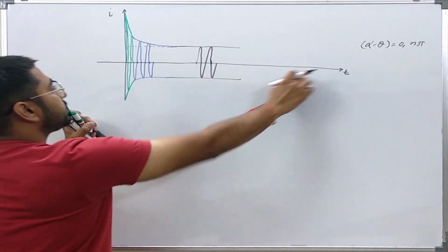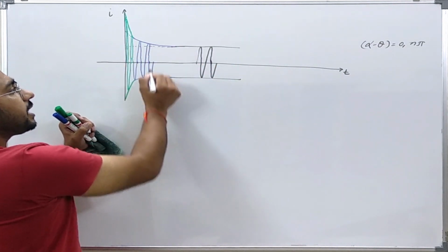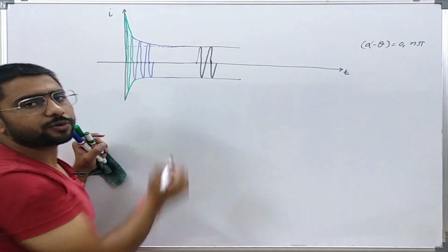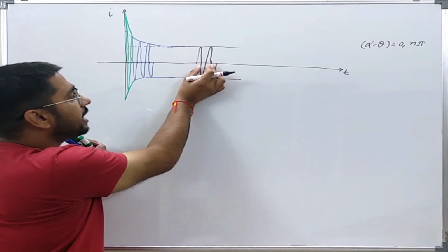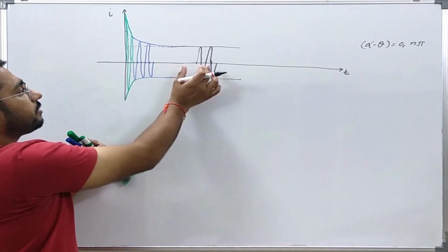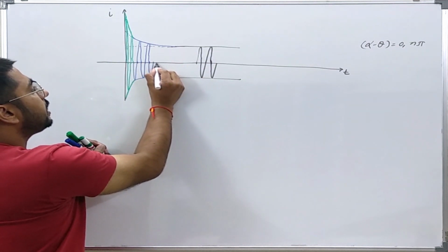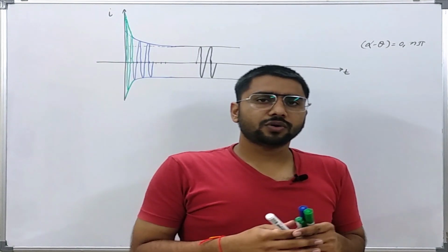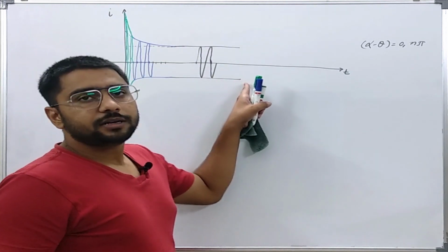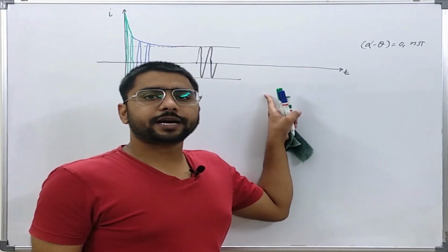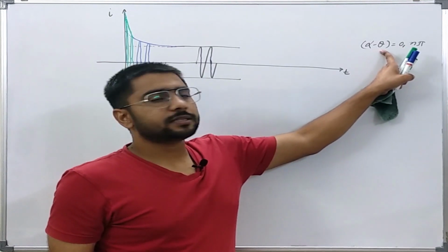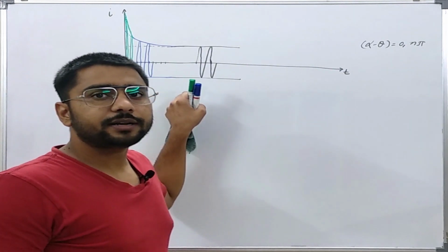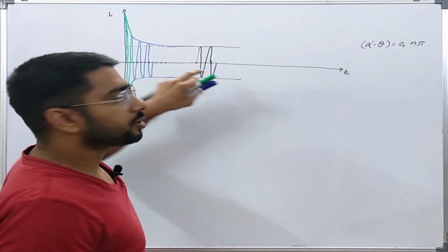Here we can see that the currents are symmetrical about the t-axis. The frequency of the currents might not appear equal due to a little bit of difference in the intervals during the drawing, however the frequency of currents is equal. These partitions are equal everywhere from here to the end point. So we should note that in the sample shown here, the DC current has not been taken into account. Either this is the case or we have just eliminated it so that we can understand the type of current appropriately for a short circuit on a generator.